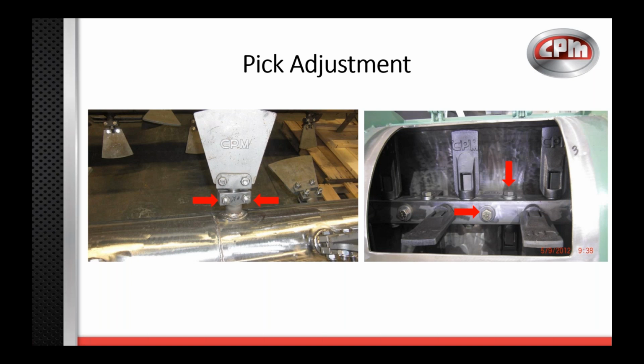So on the left, those two bolts are kind of just like a placeholder, so that tightens that shaft down. You can loosen those and then easily with your hand just rotate it to whichever pitch that you want it to be. If you need to extend that pick closer to the shell, then you would just loosen that shaft out or screw that shaft out until you get to that point where you want it to be. But then also tighten them back down.